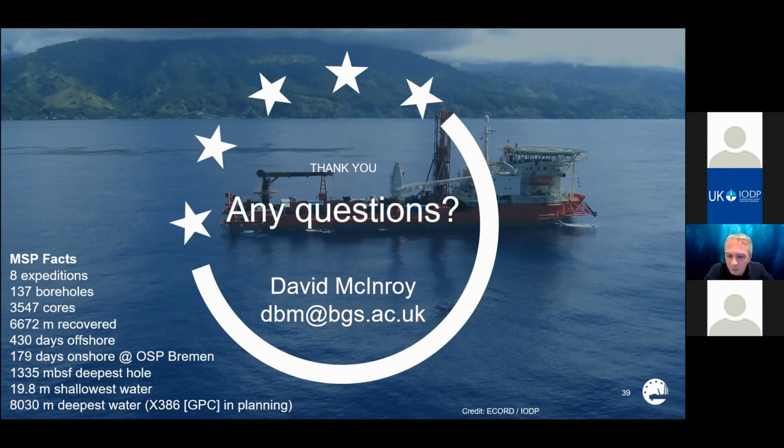So the combi float, as far as I understand it, the maximum is 56 meters water depth, and that's only with the leg extension option. I think the standard combi float is only 46 meters. So they can extend the legs a bit to get that little bit of extra water depth, but that particular combi float version of the modular platform wouldn't be able to reach that range of between 55 and 90 meters.